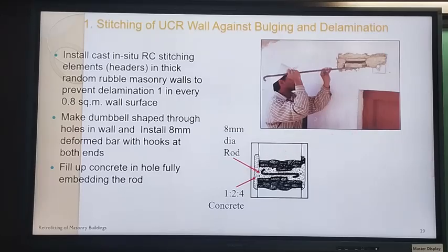Okay, and this hole making is a very delicate operation. One other thing is you don't use a crowbar. You've seen people doing that. Also, in some of the first retrofitting that was done in Latur, Professor Arya had left instructions with the irrigation department engineers. They retrofitted a house, and we visited the house after it was retrofitted. And these holes should not be bigger than about 6 to 8 inches in diameter.